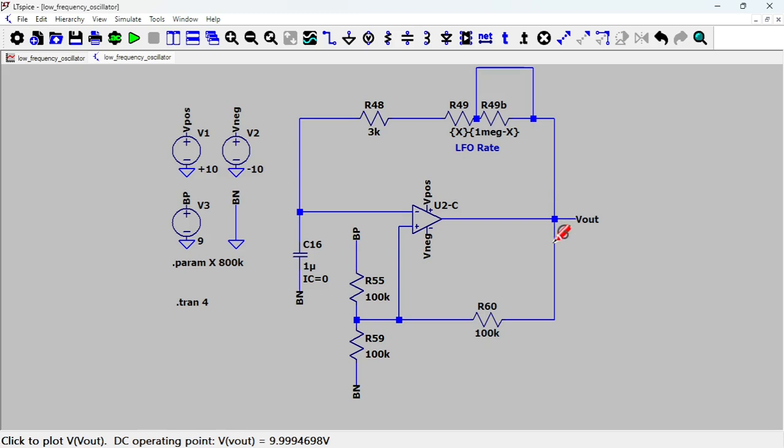Then what happens on the positive feedback loop? You have plus 10 volts, and here you have 4.5 volts. But this is not going to stay at 4.5 volts because of this 10 volt to 4.5 volt differential. Basically, there's current going in here, going this way. So the voltage divider formula doesn't hold anymore, because you now have current in this branch.